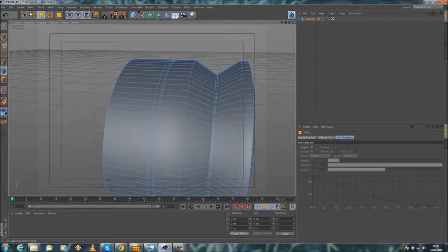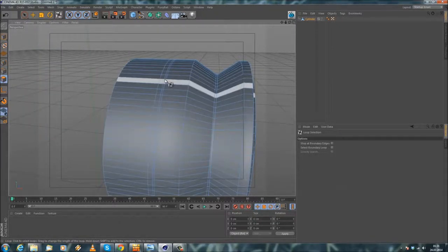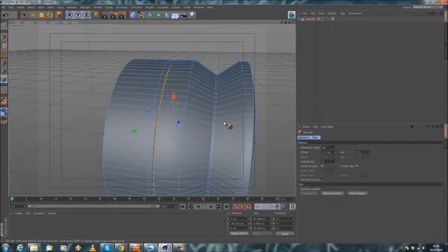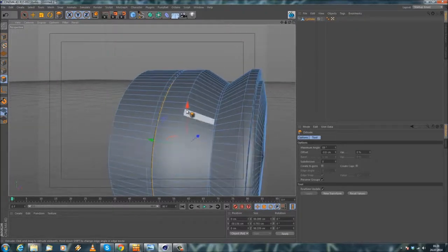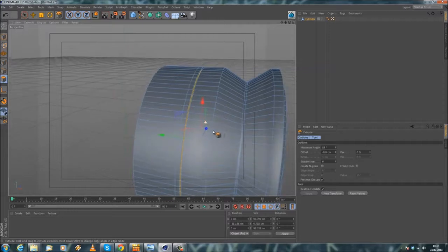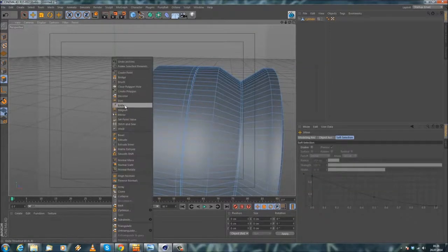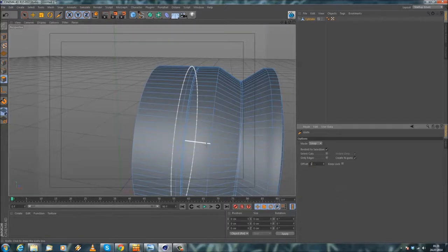Then this line, we go select loop selection, go to poly mode, select this in here. And scale this down. Whoop, no, we extrude this, sorry. Something like that, maybe 0.8, minus 0.8. Okay. Then here we have to be, okay, I think I forgot one cut. We needed to make another cut right here. So something like this. Let's type in 10%.